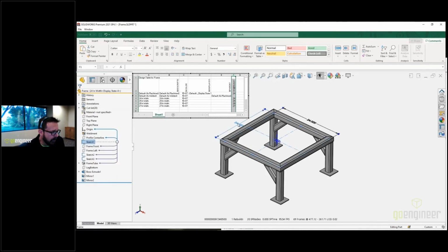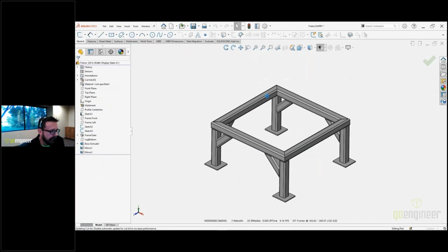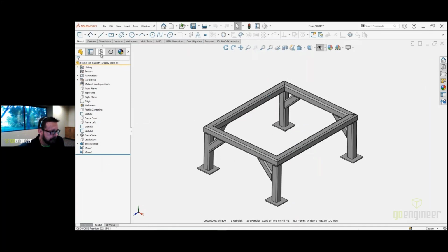And then to add other parameters, I just highlight the dimension and double click on it like that. And now that one's added as a column, right? Every column is a variable. And then I can use all the cool stuff in Excel, like copy and paste, right? So I can use incremental drag. So if I highlight a couple cells and grab that bottom corner, it'll automatically increment that variable. So, really leveraging the power of Excel, okay?